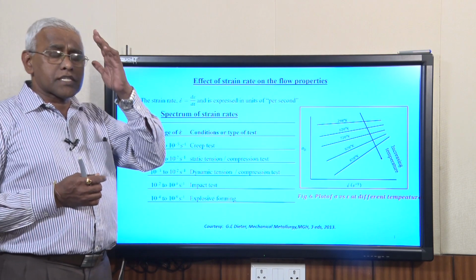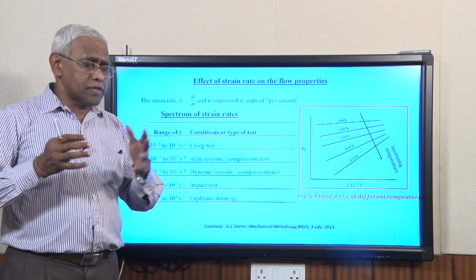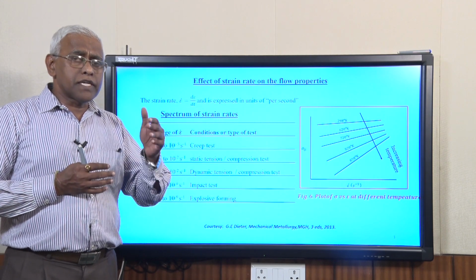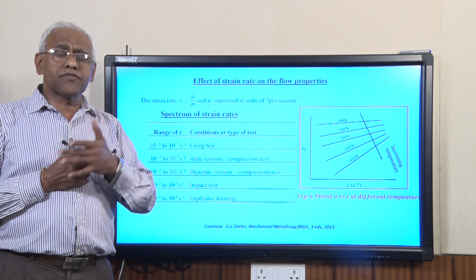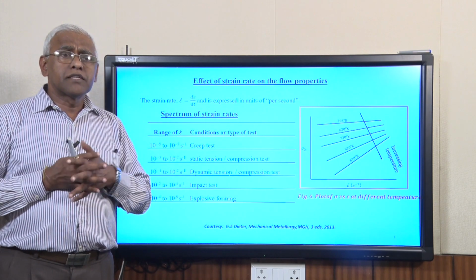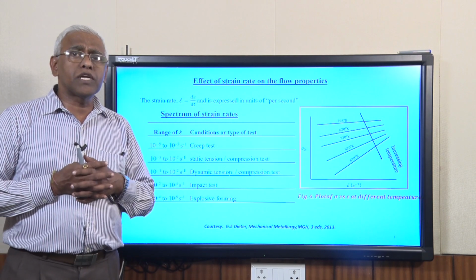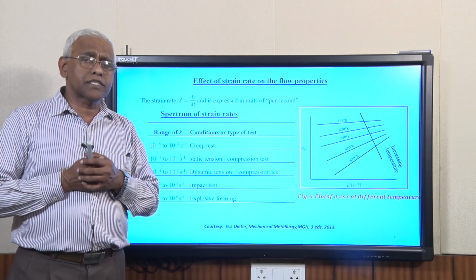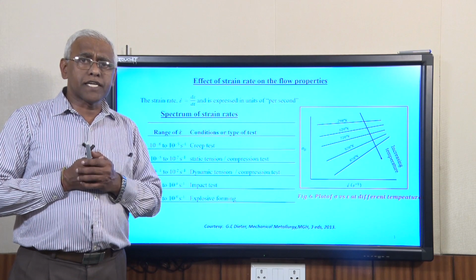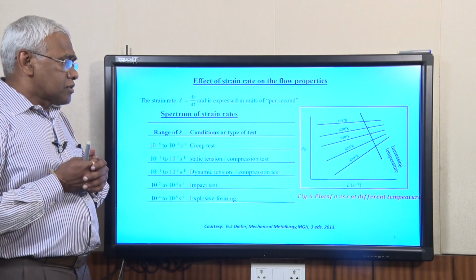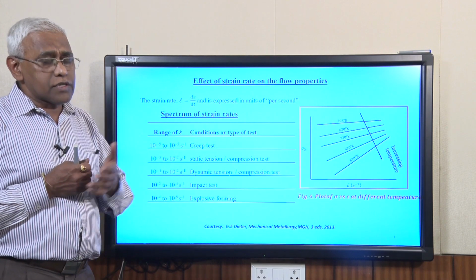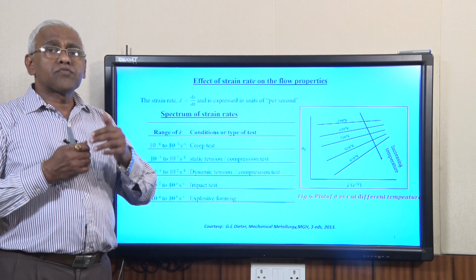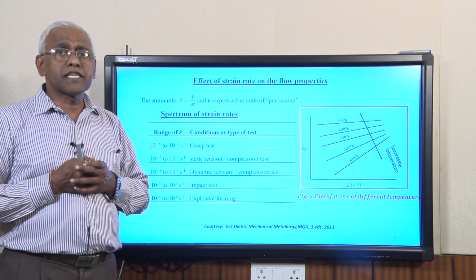So, these are subjected to high temperature and some amount of stress, and normally when you do the design of these components, say for example the reformer tube, the design life is something around 12 years at that particular temperature and pressure of application. But still you will find that by 12 years, beyond that, a small amount of plastic deformation is taking place.